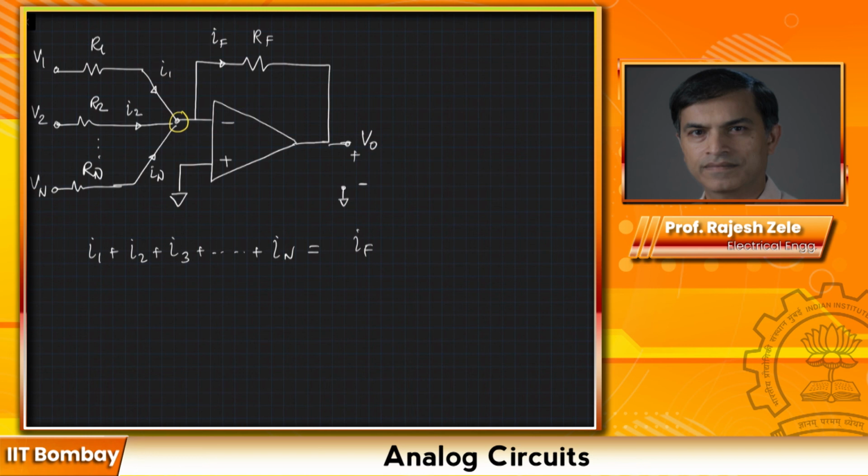So we can then write the equation V1 divided by R1. Again, why didn't I do V1 minus Vn? Vp is already 0, and because of negative feedback, this node Vn is a virtual ground. Hence I am just saying V1 minus 0 divided by R1. And now that we got used to it, I'm just going to drop this 0 term for ease of analysis.